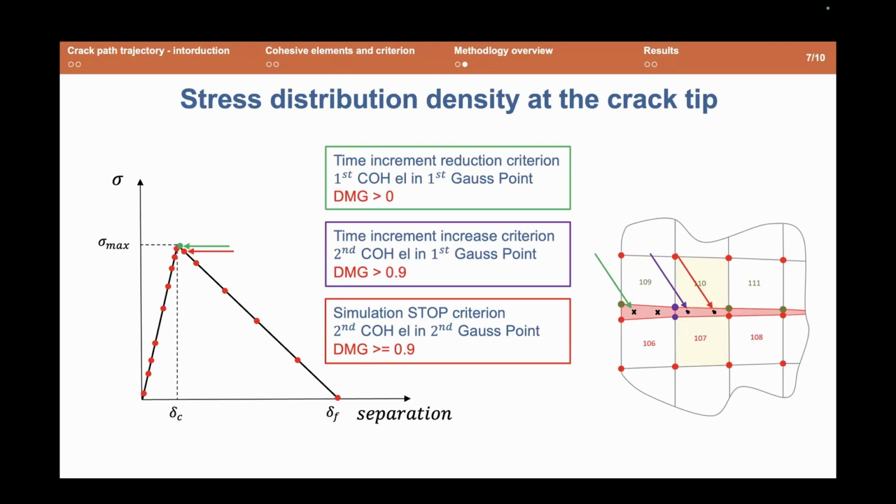It's good to notice that the whole method is mesh dependent in this way, but the mesh is tailored from simulation to simulation directly from the information about the principal stresses, and the crack goes only for the element size, and the mesh is also reduced in this zone, which gives quite nice results. And as always in numerics, if we have nice computation results, the mesh could be even finer, so even better precision.